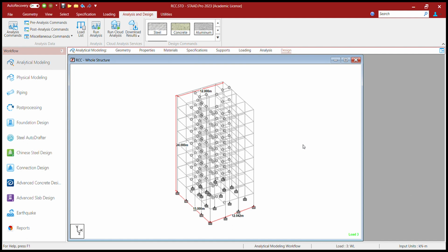Okay, select the parameters, that is FC, FY main, FY secondary, max main, max secondary, and minimum diameters, minimum size required for the main and secondary. Okay, now we'll define all these parameters. Let us consider concrete, it is of grade 30. Add. Consider main steel of 550. Add. Secondary steel 415.